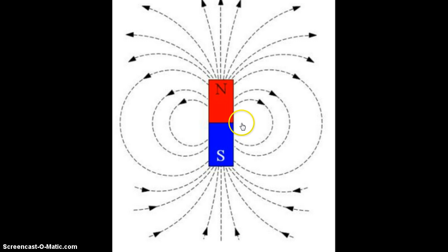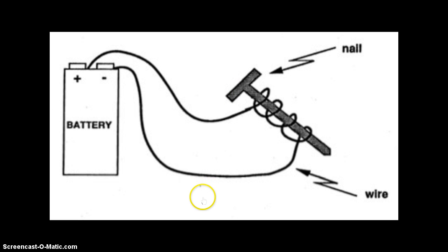But again, we can think of it going back to the back, and then looping back around to the front multiple times. And so maybe once upon a time you've played with something like this. We take a battery, our source of energy, we attach our wire, one to the positive end, current flows around and around and around the nail, and then back to the negative end. Two things. One, as we wrap the wire this way, we know it'll generate a magnetic field straight through the center. Next question is, why do I end up putting a nail in there, or what's the advantage to that?